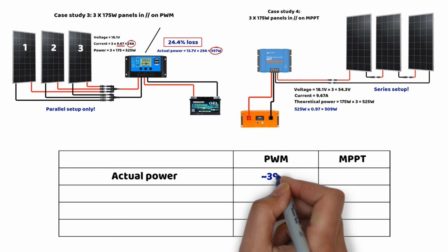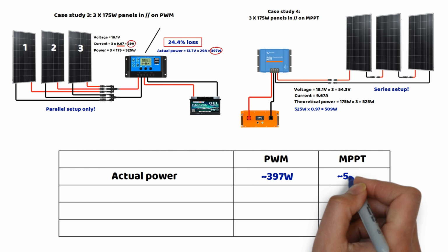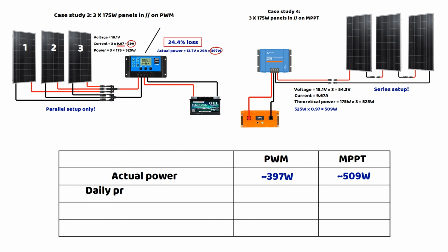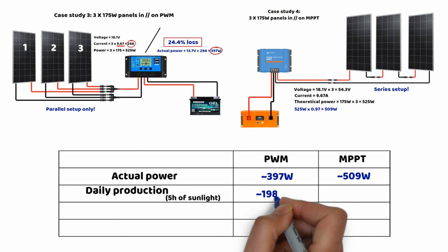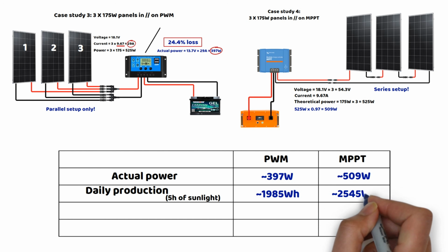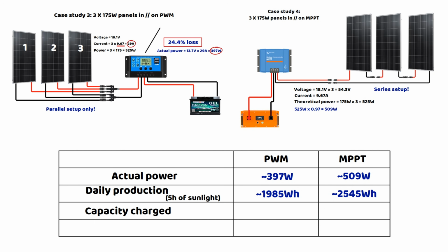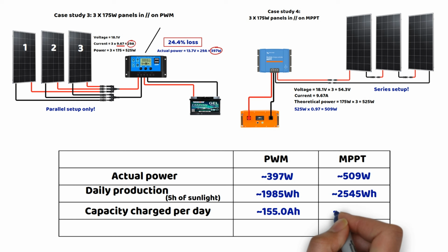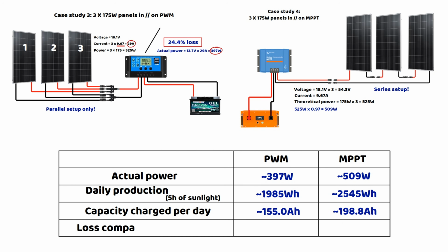What is interesting is, first of all, to compare the performance values of the 2 controllers. As you can see, an MPPT delivers much better performance because it allows the full power of the solar panels to be used. Of course, one could point out the price difference between the PWM and the MPPT. However, in some specific cases, the MPPT still ends up being cheaper overall for the entire installation.